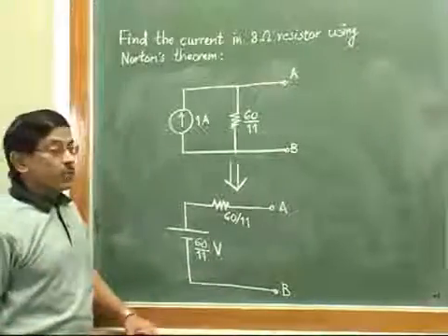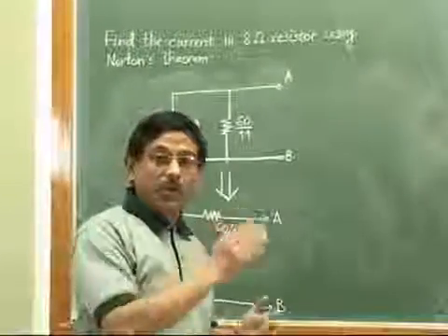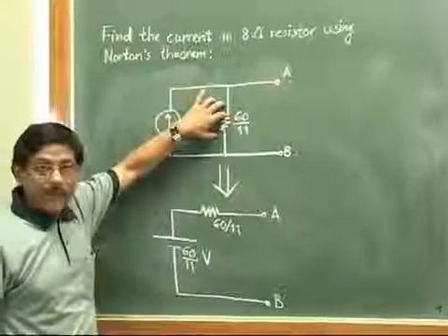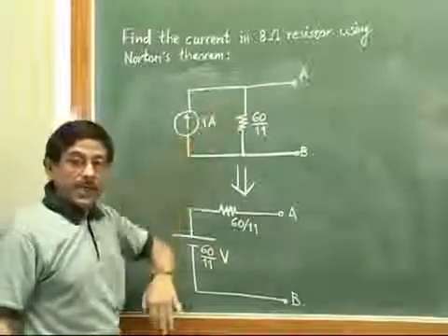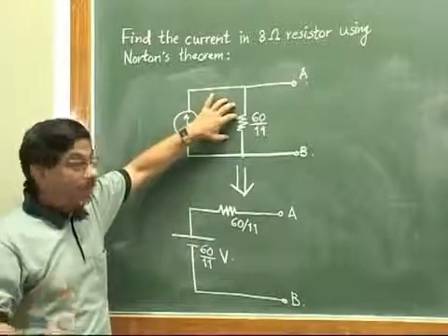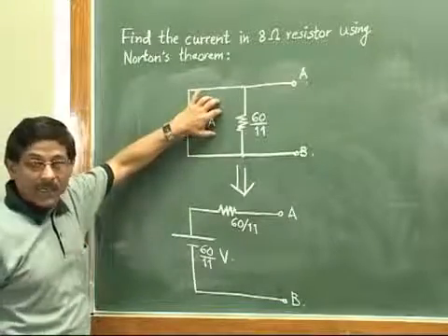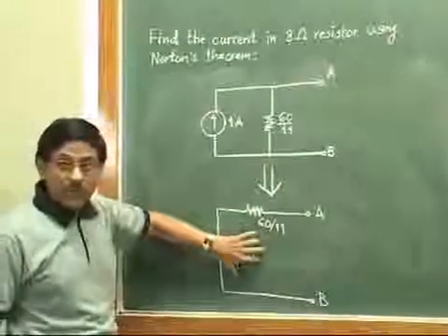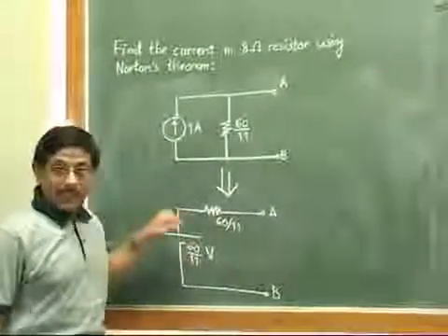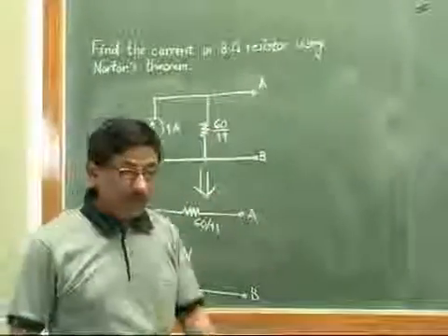That means if you solve any such problem with one of the theorems, either Thevenin's or Norton's, and you convert the equivalent circuit you finally get into the other type of source, suppose you solve the problem with Norton's and get some circuit like this, and convert this circuit into an equivalent practical voltage source, you will get exactly the Thevenin's equivalent circuit. That's why it is said that Thevenin's and Norton's theorems are complementary to each other.